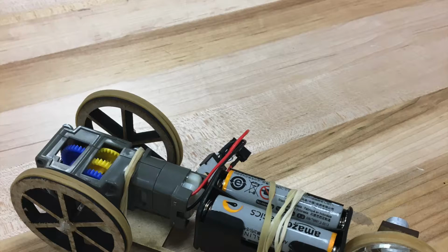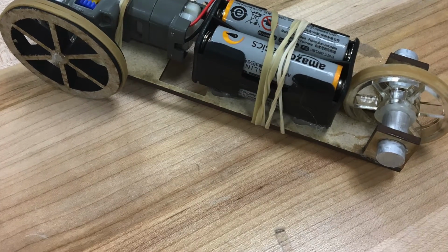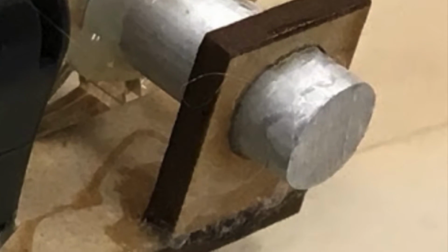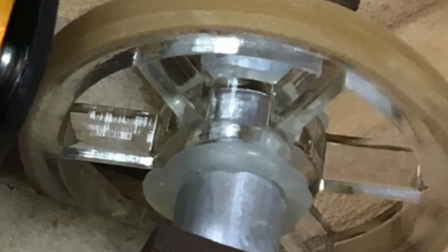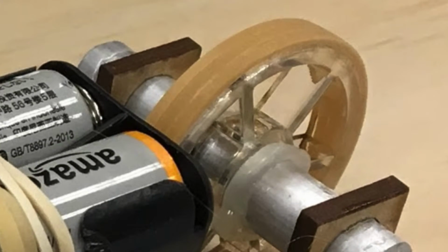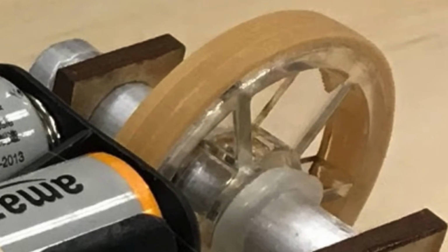While fabricating the car mostly out of laser-cut MDF, there were several adaptations that were made and obstacles that we worked around. Superglue and hot glue were both utilized to secure the battery pack, motor, and the axle supports on the car. Hot glue was used to create spacers that secured the front wheel and prevented it from sliding on the front axle. Rubber bands were also used to attach the battery pack and motor to the body of the car, in addition to lining the wheels to add friction.